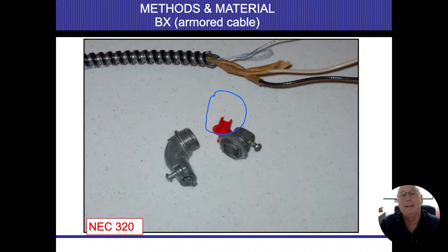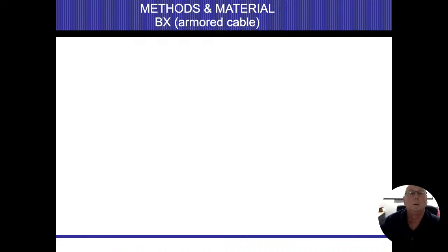The extra wire that's in there isn't really a separate ground wire. We tie everything together to give us our grounding system, but there's not going to be an extra ground wire in there as well. The armor cable comes in short whips, 5 feet. We should be able to see that bare metal piece folded over and folded back, so that we know everything's connected and we have one continuity coming across.